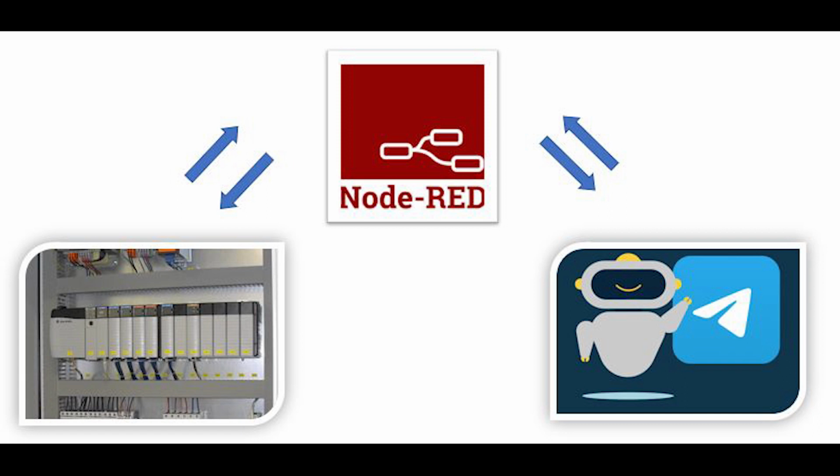The bot reads the user commands and orders and sends them to Node-RED, which translates them into signals that the PLC receives via the internet. All the parts are interconnected and feed off each other, so the PLC receives information from Node-RED and Node-RED receives information from the PLC, depending on the user requirements.